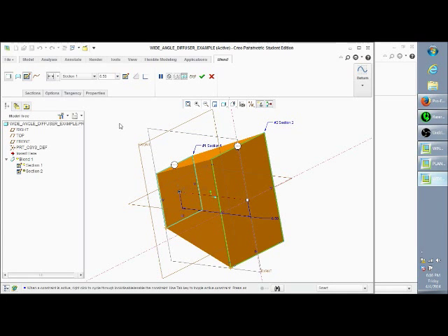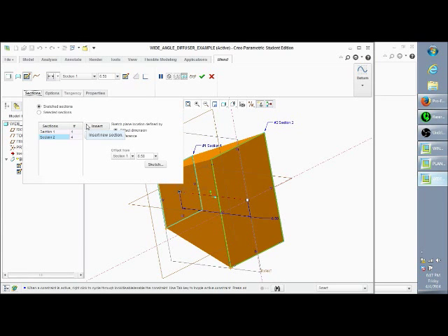Remember when I mentioned earlier, I said we were going to start creating a straight blend? What I mean by that is that here you have two different options for your blended surfaces. Since we are only going between two boxes, it doesn't really matter which one we select now. Just for the sake of consistency, I'm going to select the straight one, but I will show you guys later exactly what that other option, the smooth option, does, because it can easily give you the shape that you do not want. The same goes for the straight, depending on what kind of shape you want to make. So we're done with these two right here.